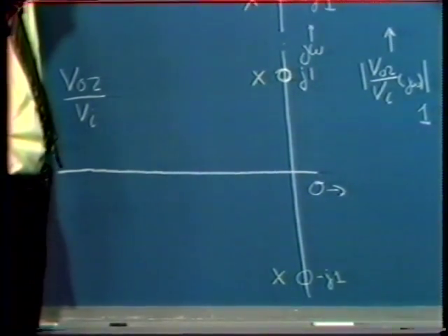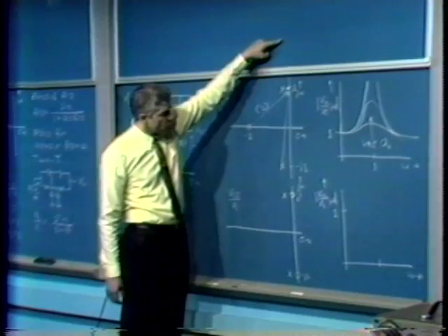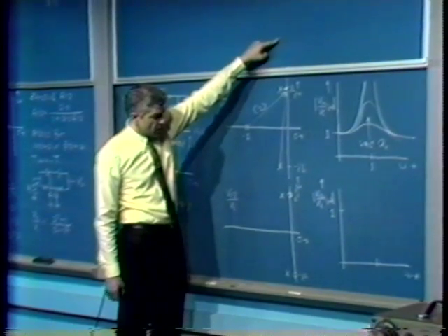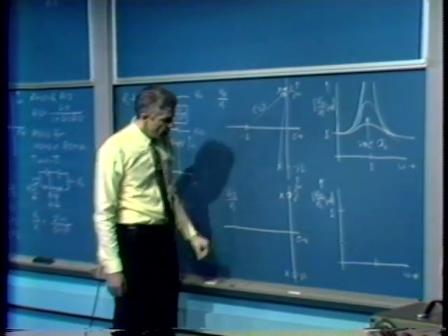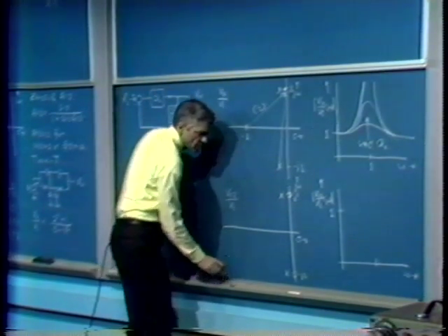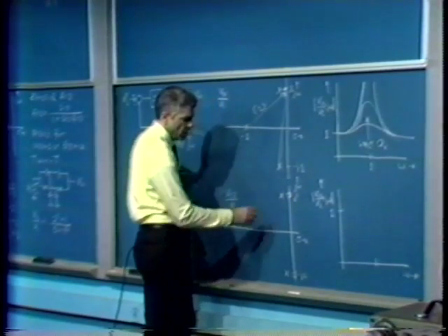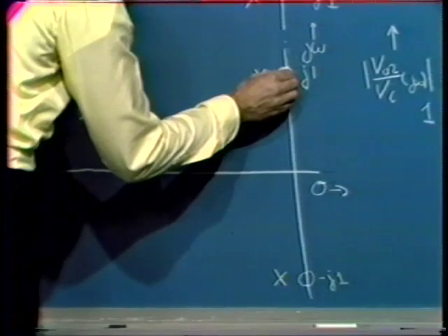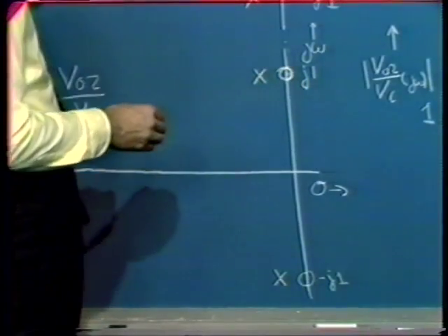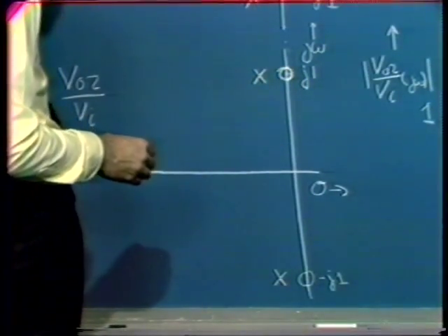At very high frequencies, when we evaluate this transfer function for sinusoidal steady state response, again, the vector lengths cancel. And the only difference occurs, again, at points near the location of the pole and zero pair. When we look, for example, at the frequency right here and ask for the frequency response, it must go to 0.